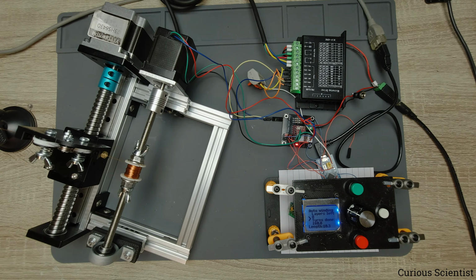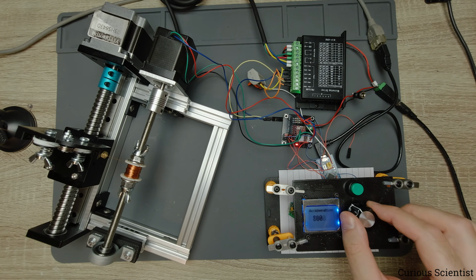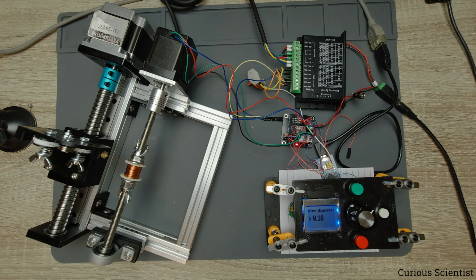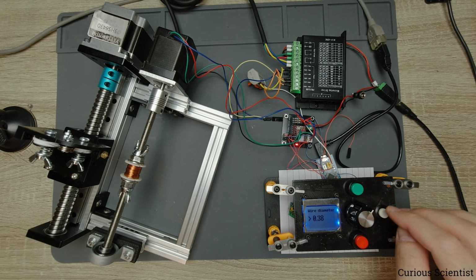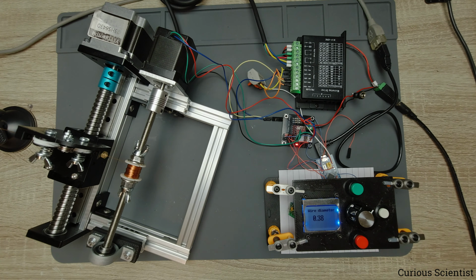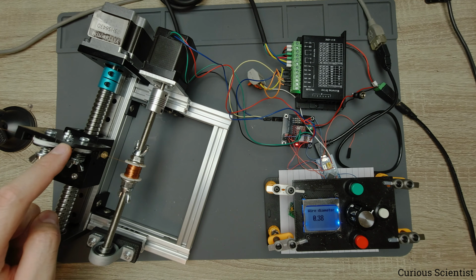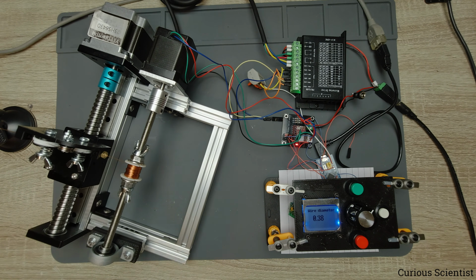So this could have been one problem. To overcome that problem, it's maybe beneficial to measure the wire diameter and then add that input value to the software, so the software will calculate everything properly. So now it's 0.38, and then this will move a bit faster because then the coil is built also faster. But then, of course, the number of layers will be different and so on, because there will be fewer turns within one width.